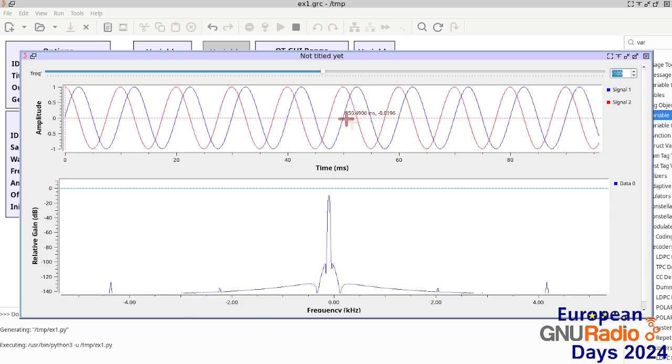So the imaginary voltage, of course, does not exist. We only have a real part and an imaginary part because we've created an IQ demodulator with I and Q, two quadrature local oscillators, cosine of omega local oscillator t and sine of omega local oscillator t. And these two voltages can be probed by an oscilloscope. They are real voltages, but they happen to match the imaginary algebra where the cosine and sine are in quadrature.